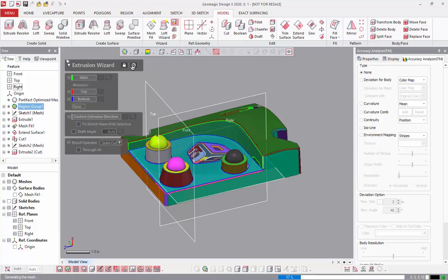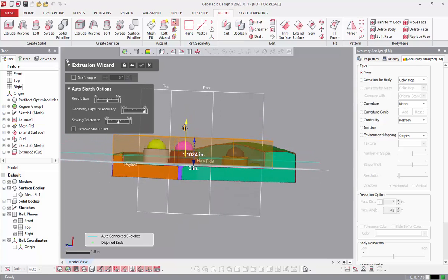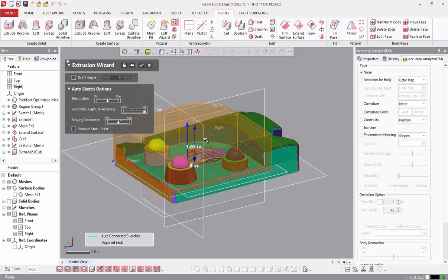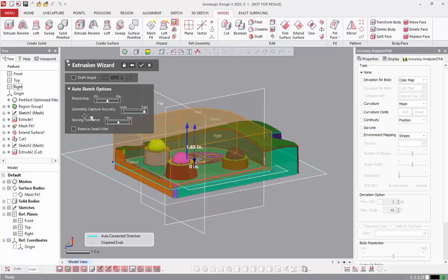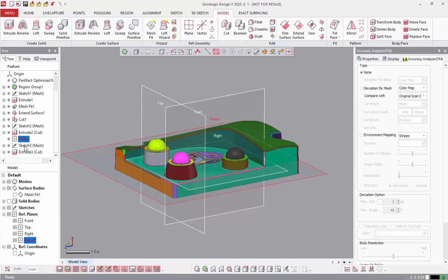Now, if I hit next stage, of course, that's just going to generate a preview for me. And here I can alter a number of things, including the value or height of this extrusion, and some other things with my mesh sketch as well that it generates, and hit OK. Now, Extrude 2 is the last feature that I've generated in the feature tree, so we're going to see a number of things populate in my history tree after I hit the checkbox. So hit that, and the software builds me underneath Extrude 2: plane 1, sketch 3, Extrude 3.